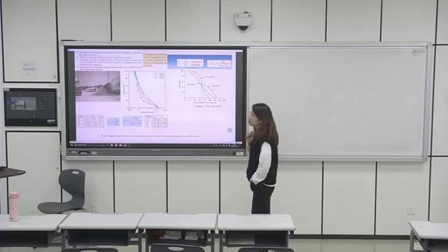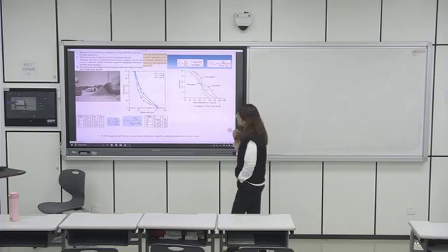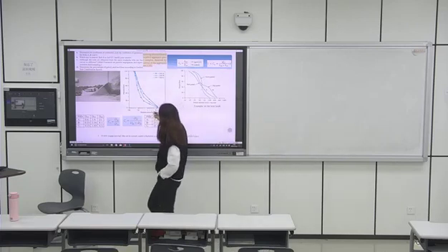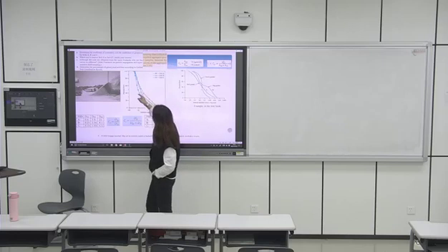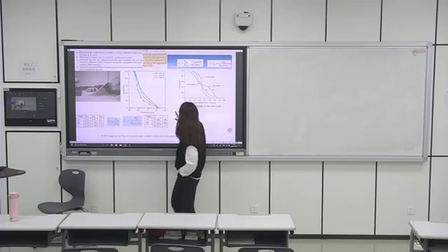We say coarser means that the soil has many more big particles, right? We say gravel is coarse, right? That means the soil is rough, having big particles. So you see in here, big particles, of course, soil A has more big particles. Let's see if you find 1 millimeter. You can find 1 millimeter in here, right?